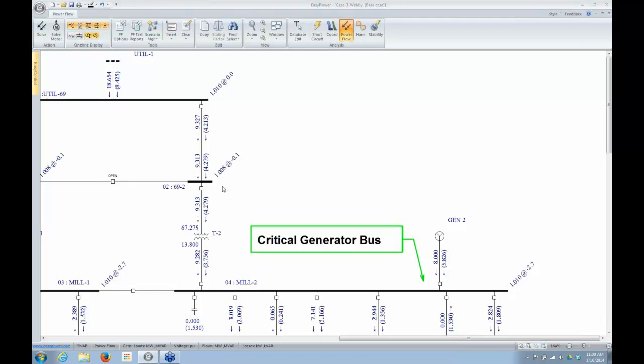There is power loss by heat. The program is going to calculate the losses in the electric system, so it will show you the losses in the system. If I look at this transformer, this is the kW losses. These are the VAR losses. This is where the VARs are being consumed, basically, in the transformers. So as far as what you would do with that information would be really up to you at this point.